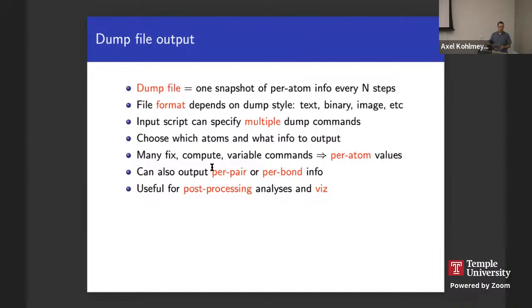There's many ways to get per atom output. It includes some fixes, computes, and variables that will dump per atom values. You can also output per pair and per bond info to a dump file. And this is really useful for post-processing if you want to visualize your simulation.